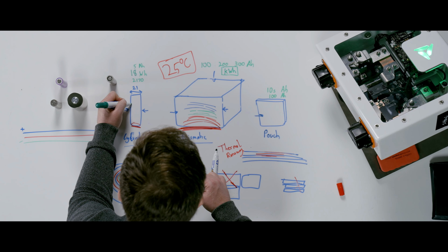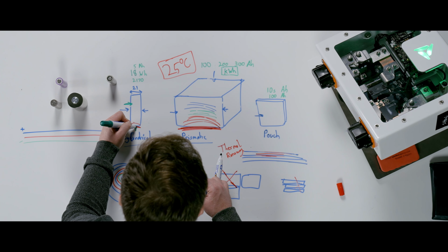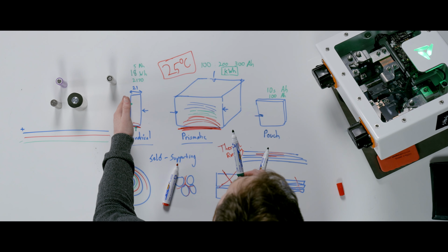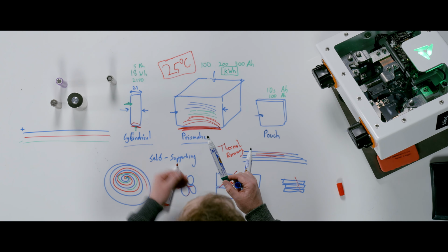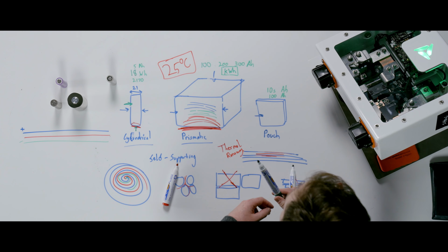So actually, cooling the side of the cells here might not be the best, because you've got a very high thermal resistance going this way versus going this way. But in all real practical packs, getting the most contact area on the battery cell, and for other pack designs, it is actually in practice better to cool from the side of a cylindrical cell in all real-world applications and real-world examples. With large prismatics, the same applies.